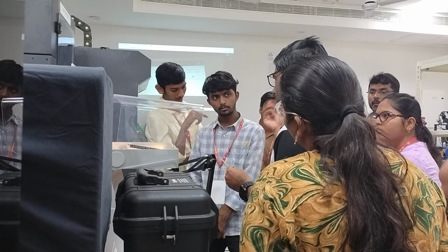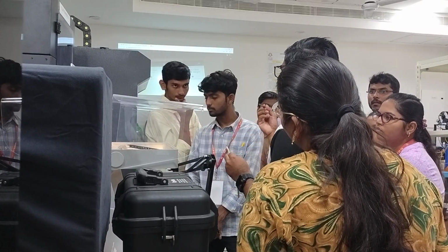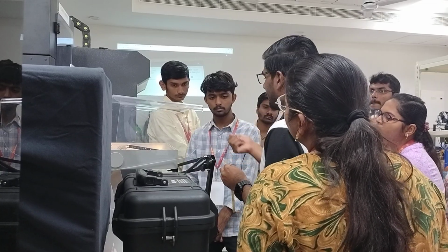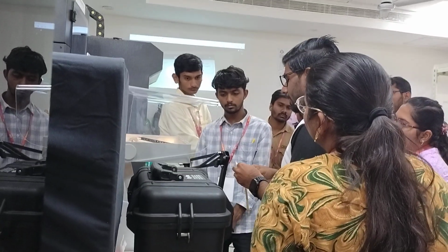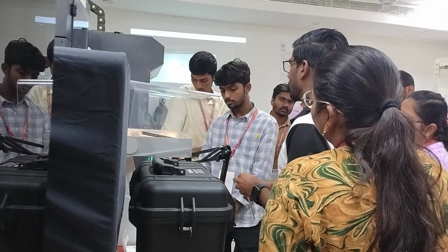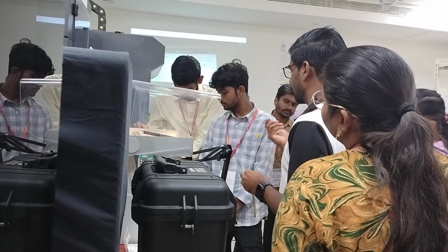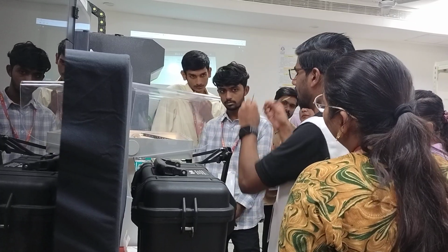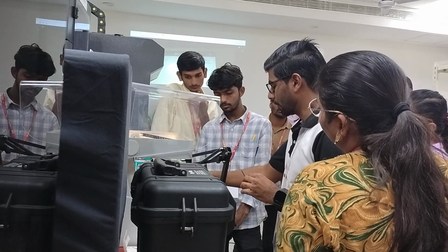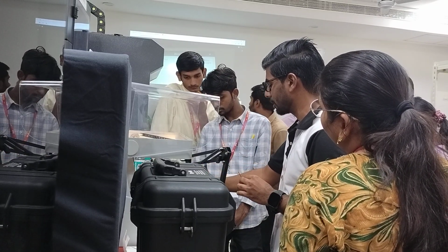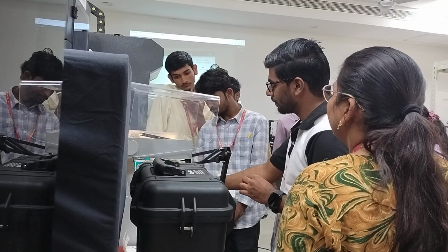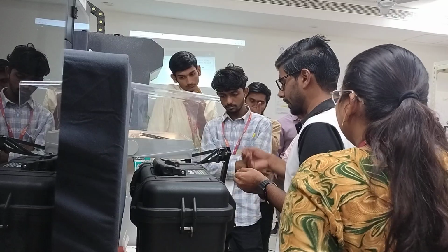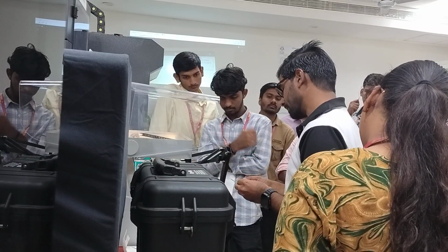Yes. So these shims are basically used to find the clearance between any two parts. We cannot use verniers everywhere, and if there are small gaps, we cannot put the vernier or the gauges there. In that case, these shims are already well defined, and we just put them in those places and see if there is a small resistance. Then we say, okay, the thickness of that measured part is so much. That is basically called a shim.